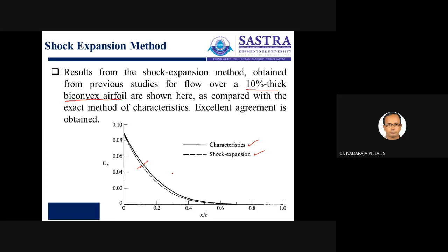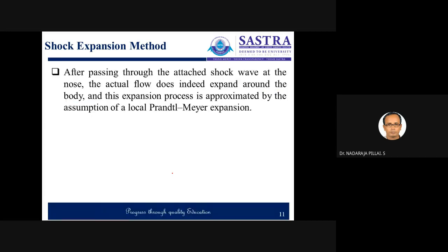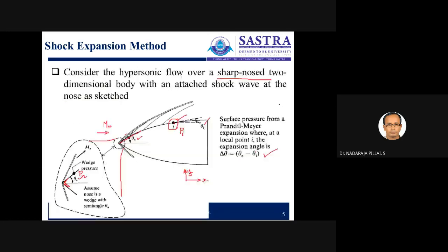Okay. So let us have a discussion. How can we apply this shock expansion method for supersonic and hypersonic flow, right? Here we made a very strong point that after passing through the attached shock wave at the nose, the actual flow does indeed expand around the body, and this expansion process is approximated by the assumption of the local Prandtl Meyer expansion. Right? So, by that way, we have calculated everything.